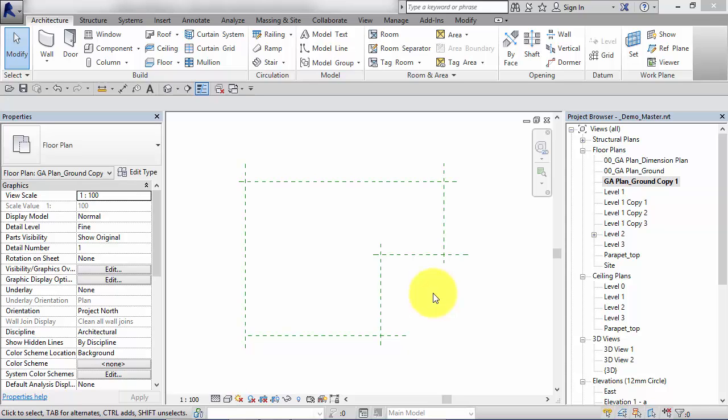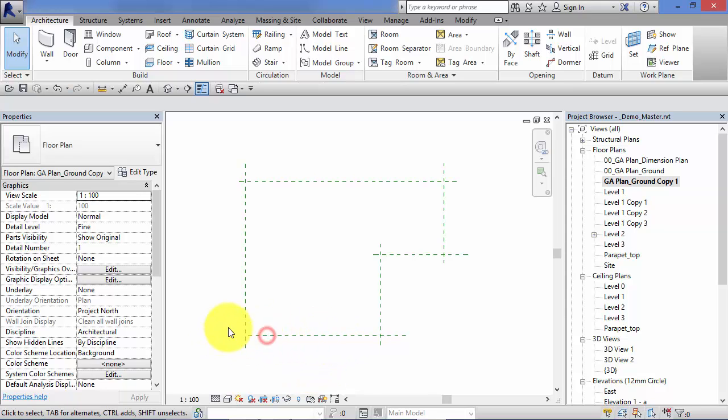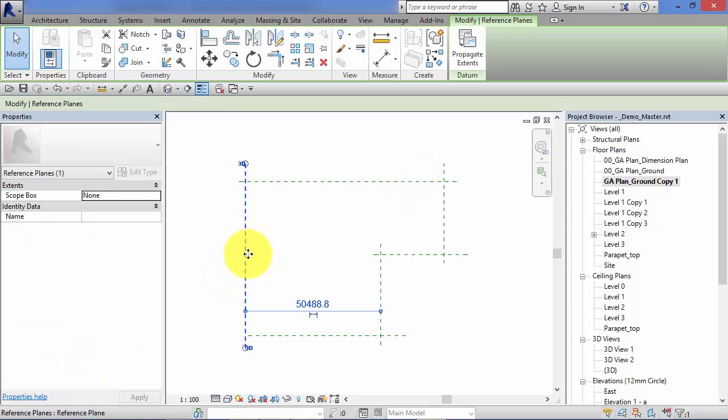So we said one use of reference planes in Revit was as construction lines, i.e. to help set out our building. Just going to show you how that works in reality now. So here are the reference planes that we've previously set up. So we can fine-tune their position. If I select a reference plane, I can drag it into a new position. You'll notice when I select that reference plane, I get a blue temporary dimension that comes up. I can change the value in there. I'm going to go through temporary dimensions in detail in a forthcoming unit on drawing aids.